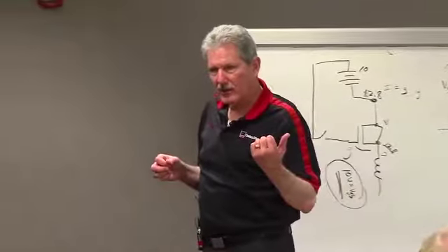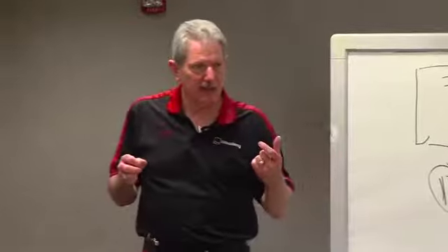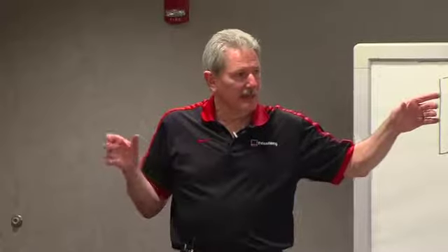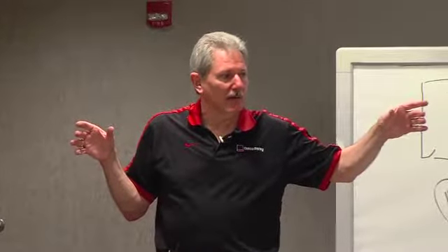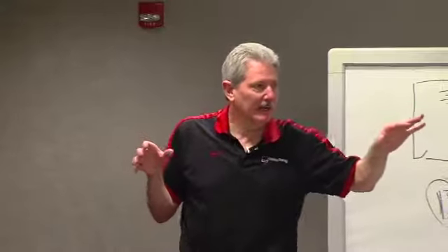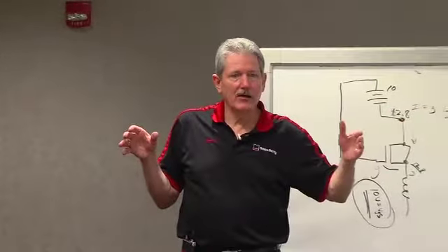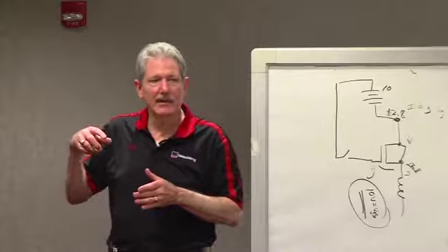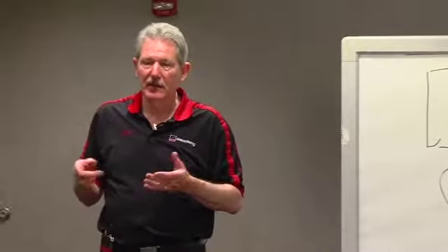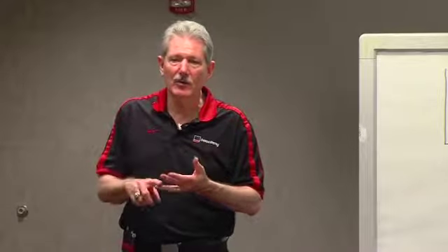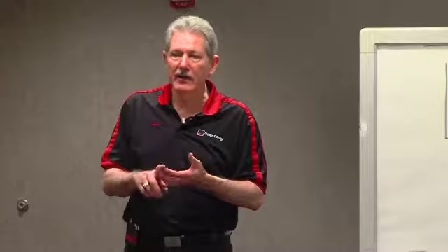And I already said my closing 5 minutes ago, but let me say it again. From 1968 to now, regulators have changed. Instead of being a simple device, now they are an integral part of the energy management system. Charge on decel, wide open throttle shutdown, communication.